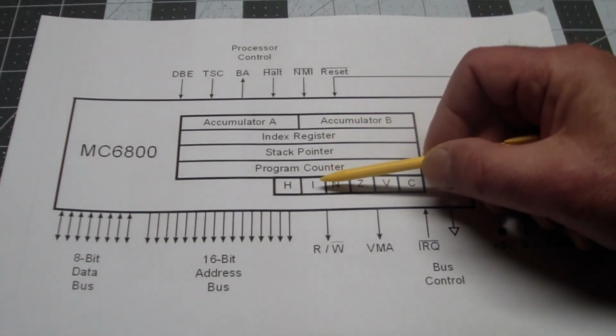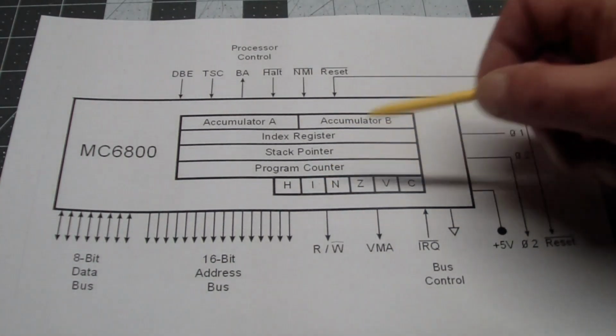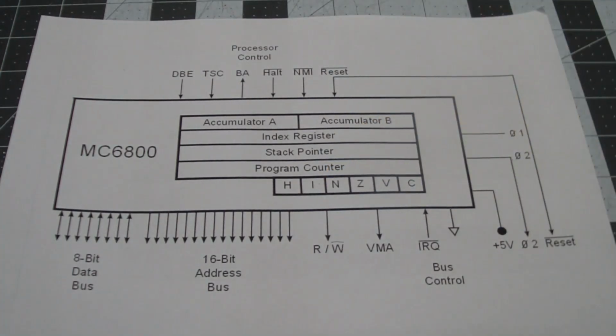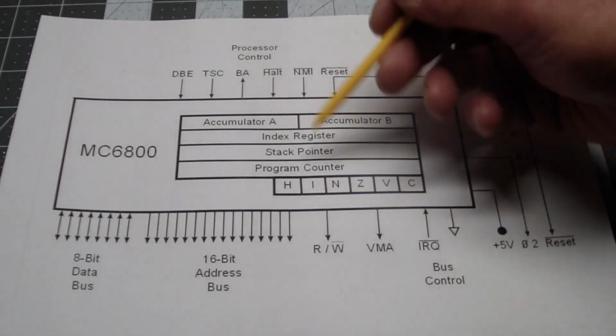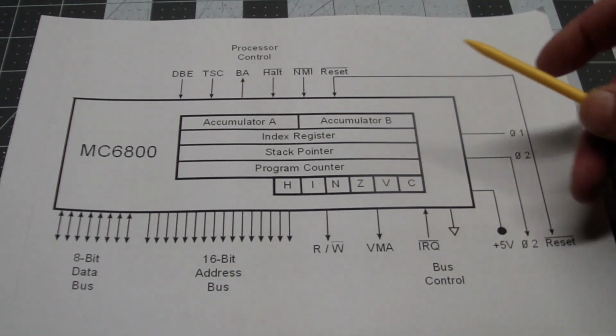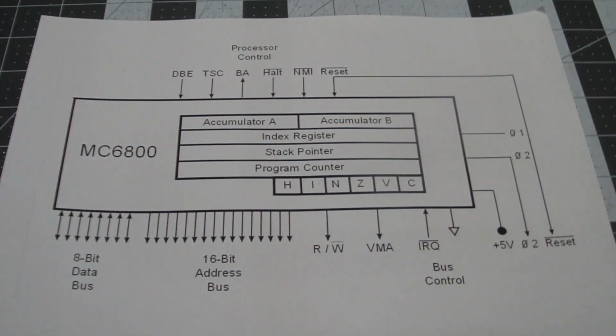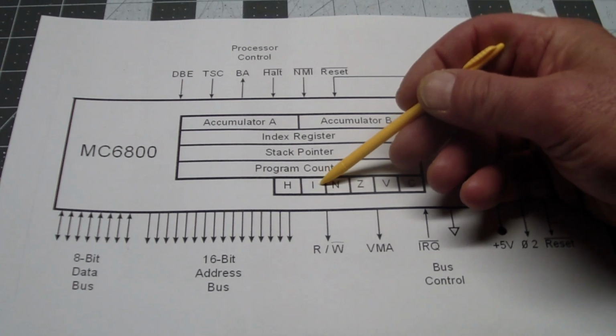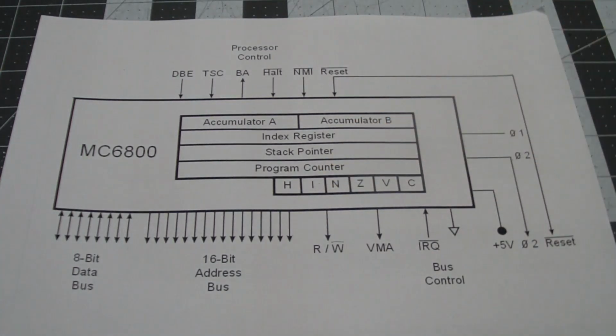It is essentially blocked, and after resetting the processor, the interrupt flag is set. So you kind of want to wait until the processor has internally initialized itself before you allow interrupts. Interrupts are going to occur anyway if they're hardware generated, but you're preventing the processor from receiving them, and it is under your control when you want to allow them by resetting this flag.